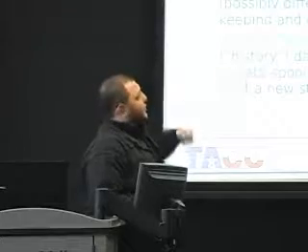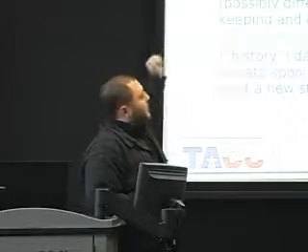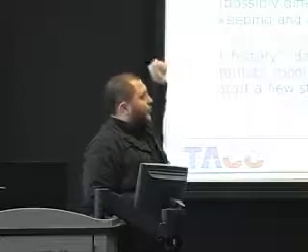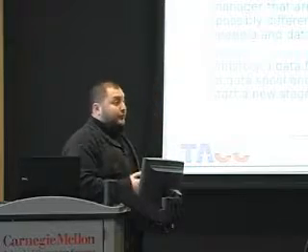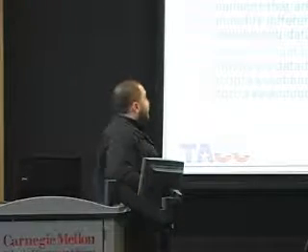And we have two reservoir simulators. We have Cactus Black Oil, that is based on the PETSc Portable Extensible Toolkit for Scientific Computing package and the Cactus Code framework for high-performance scientific computing. And, of course, Defiant, which is based purely on PETSc. You also need the actual ensemble Kalman filter, the piece of code that computes the Kalman gain matrix. And we've written that because it's very simple linear algebra. We've written that in PETSc because PETSc handles linear algebra in parallel, so that's advantageous.